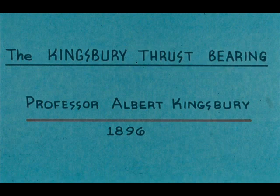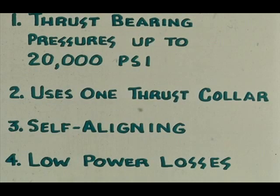His first commercial product was installed in a vertical shaft turbine in 1912 and was still running 40 years later. The Kingsbury thrust bearing eliminated or reduced many of the limitations that were imposed by the old collar and block system.